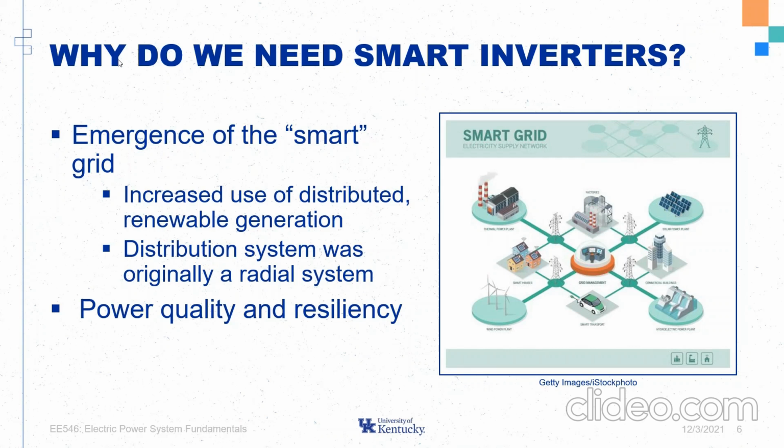Additionally, the smart inverter fixes an issue that has caused renewable energy sources to be a detriment to the power industry. Faults happen in the grid, and most are only temporary. However, when a traditional inverter experiences fluctuations due to faults, it severs itself from the grid. By doing this, generation is removed from the system, causing a further imbalance. This can have a cascading effect that causes more inverters to sever themselves and could lead to a blackout. The added capabilities of a smart inverter help it to weather these small temporary faults. Instead of contributing to the problem, smart inverters allow renewables to be part of the solution.